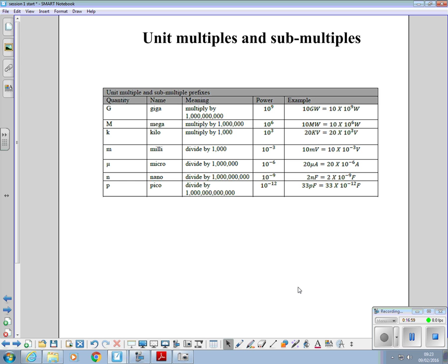If all your quantities are in the same multiple, then you can just put the numbers in and the answer will be in that multiple as well. So if you've got millivolts, milliamps and milliohms, just put the numbers in the formula and your answer will be a multiple milli. But if they're different, then use the power of 10 notation carefully with your calculator.